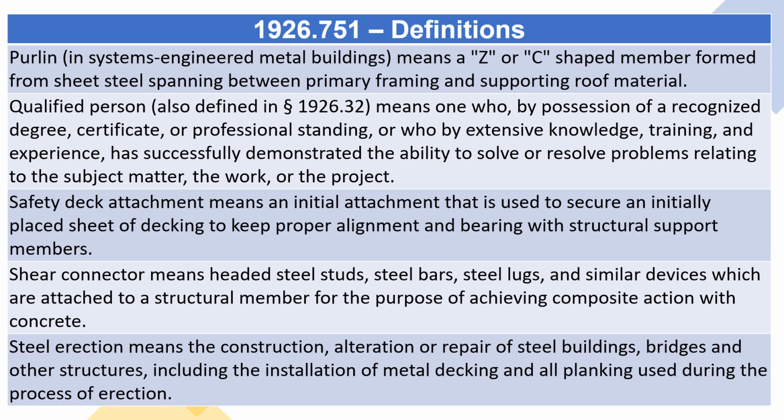Safety deck attachment means an initial attachment that is used to secure an initially placed sheet of decking to keep proper alignment and bearing with structural support members. Shear connector means headed steel studs, steel bars, steel lugs, and similar devices which are attached to a structural member for the purpose of achieving composite action with concrete. Steel erection means the construction, alteration or repair of steel buildings, bridges and other structures, including the installation of metal decking and all planking used during the process of erection.